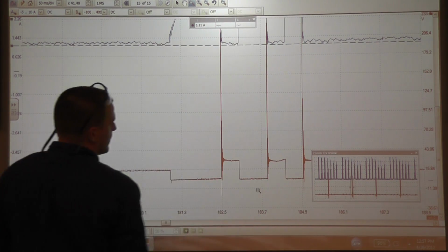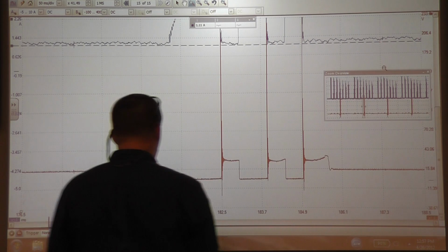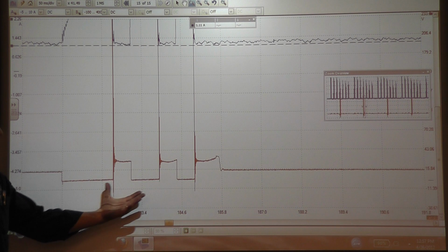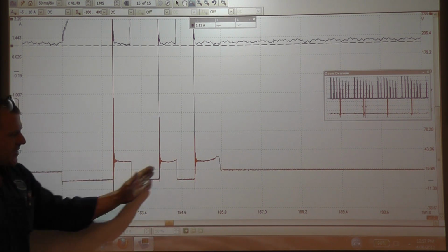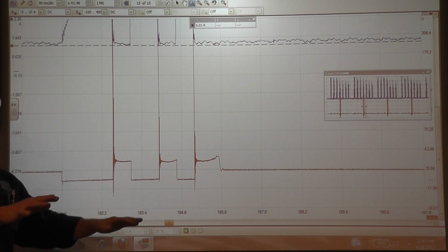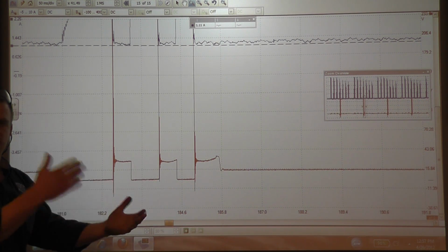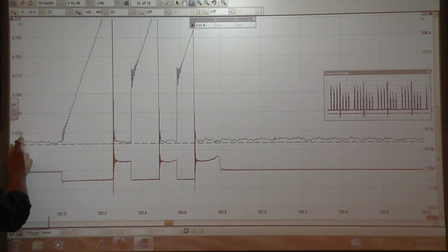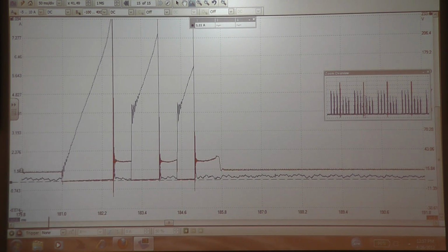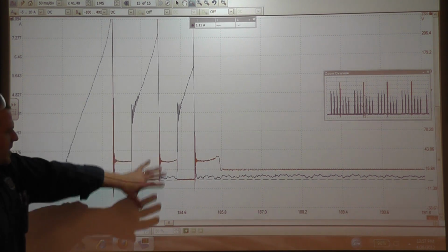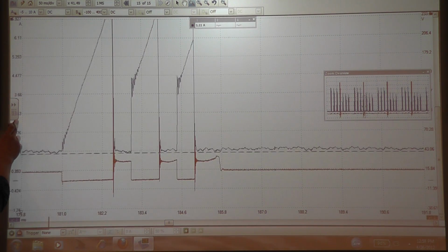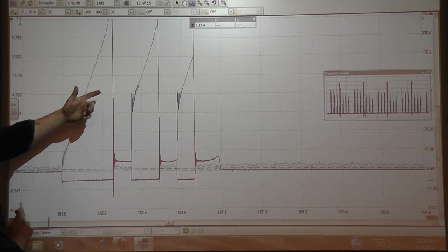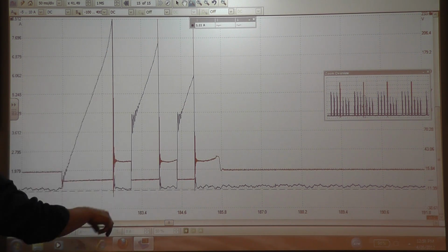This is, again, a primary waveform. And that is a multi-strike discharge system where it fires 3 times. This is basically a low-speed operating condition. Once you go above 1100 RPM, this goes away and converts back to a conventional single-strike system. So that matches, if we follow our amperage waveform, you can see they go right over top of each other. 3 different amperage ramps occur at the same time these voltage waveforms are occurring. The spike is the collapse of a magnetic field, and that would be when the current flow stops. As you can see in this picture, current flow, shut the current off, we get a spike.